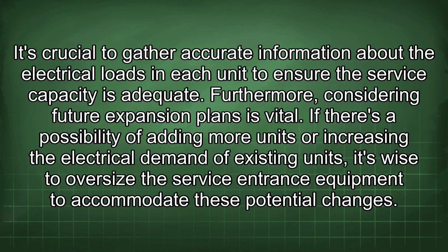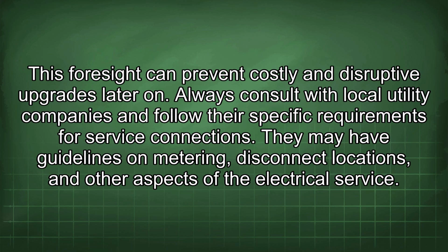If there is a possibility of adding more units or increasing the electrical demand of existing units, it's wise to oversize the service entrance equipment to accommodate these potential changes. This foresight can prevent costly and disruptive upgrades later on. Always consult with local utility companies and follow their specific requirements for service connections. They may have guidelines on metering, disconnect locations, and other aspects of the electrical service.